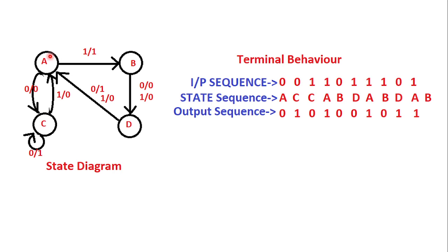So here a transition happens from one state to another state only with reference to the clock cycle. Let's say it is remaining in the A state. When it is in the A state, it has an output which is nothing but 0. When we indicate 0/0, that does not mean that the output is available only during the transition. Outputs are always available with that state.